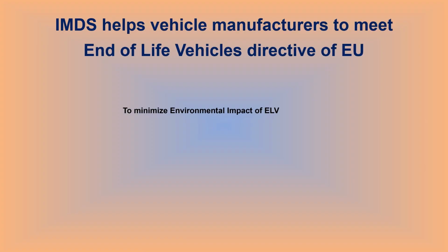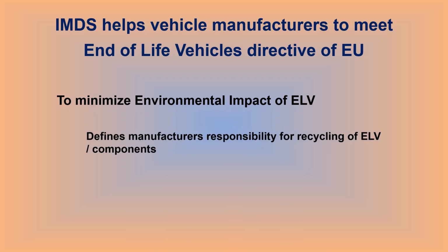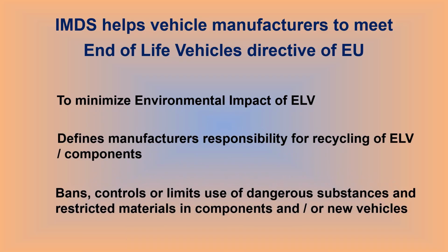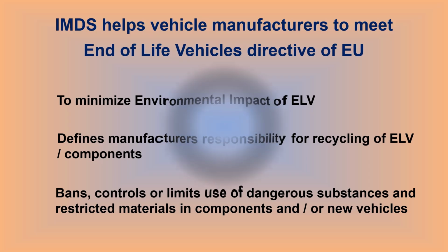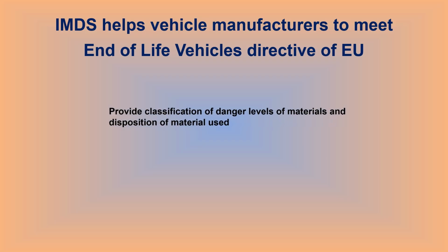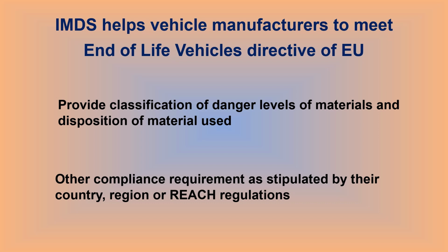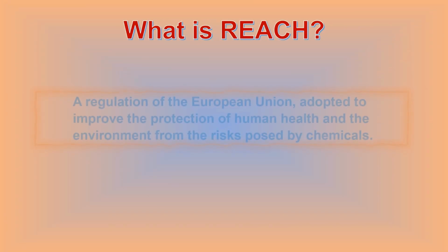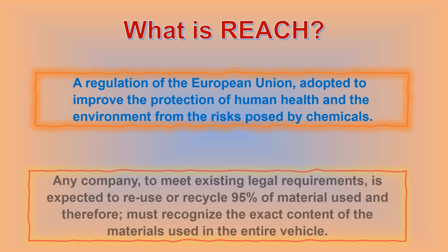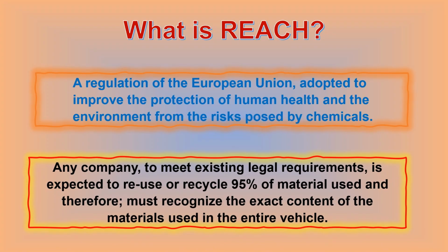It defines manufacturers' responsibility for recycling of ELV components. It bans, controls or limits use of dangerous substances and restricted materials in components and/or new vehicles. IMDS provides classification of danger levels of materials and disposition of material used. It also helps with other compliance requirements as stipulated by their country, region or REACH regulations. REACH is a regulation adopted to improve the protection of human health and the environment from chemicals. Any company, to meet legal requirements, is expected to recycle 95% of material used.